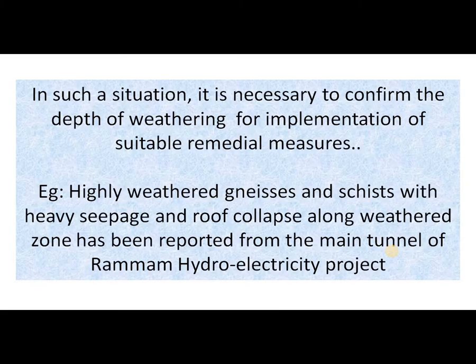In such a situation, it is mandatory to confirm the depth of weathering for implementation of some of the remedial measures. Highly weathered gneiss, highly weathered seams with heavy seepage and roof collapse along weathered zone have been reported from the main tunnel of Ramam hydroelectric project. So, weathered rock poses so many problems.